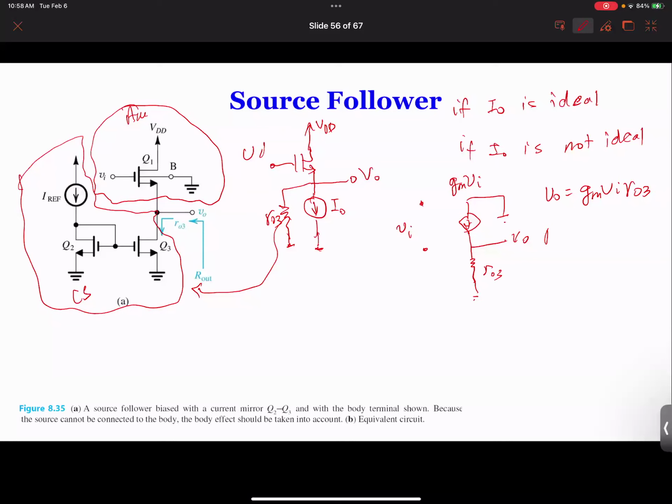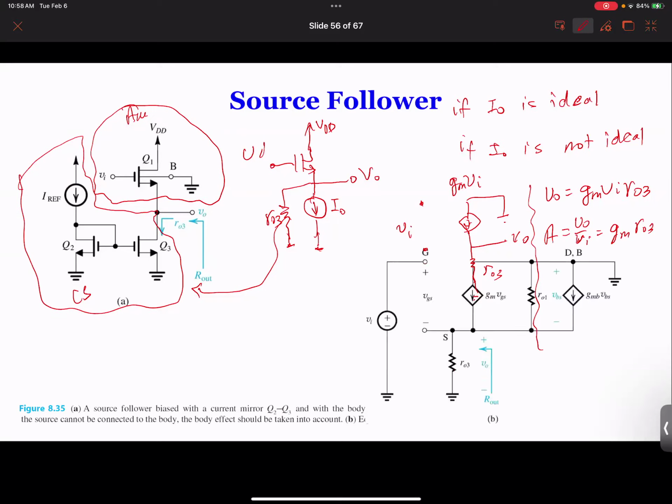And your gain can be calculated as VO/Vi equal to Gm times RO3. It depends on the value of RO3. This gain can be typically quite small. So in the book, we have redrawn the whole circuit that includes also RO1.